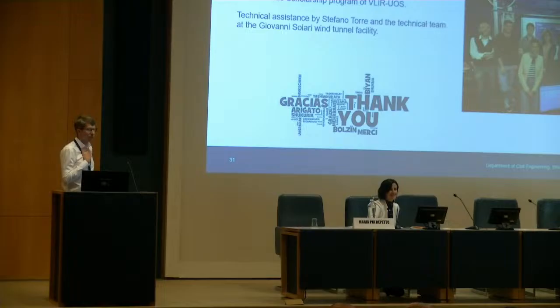So you put the model horizontal, like the lattice tower model, and then in full scale, if I'm not wrong, it was like 80 meters high. So basically there could be effects due to not simulating the standard ABL profile or thunderstorms. Yeah, so we indeed chose to do a test on a section rather than a scaled down version of the full model.